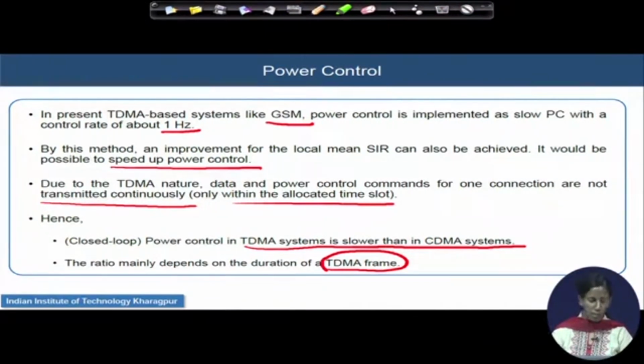What you are trying to understand from the last two slides is basically the summarization of the effect of power control. We understand that the uplink power control is absolutely essential to control the inter-cell and intra-cell interference, to mitigate the near-far problem, and also to mitigate the fast fading effects for pedestrian users. Compared to uplink, in some cases we also do the downlink power control, but the downlink power control does not have that much effect in improving the total performance of the CDMA network.